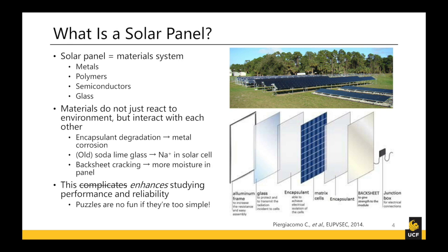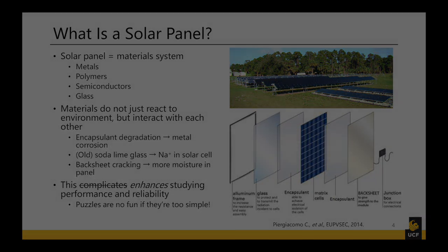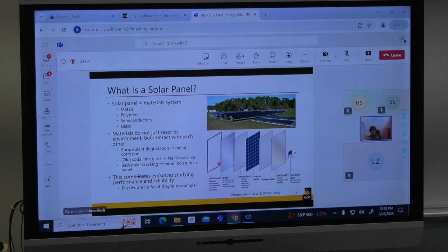And to give a little bit of an overview, this is historically the module architecture that you'll probably see most, since we have decades of panels that have been outside. And the more contemporary technology is not too different. So you have this sandwich where you have these, they're called cells that actually produce the power, all sandwiched with polymer layers, a glass polymer or two glass layers, and then wrapped together with an aluminum frame.